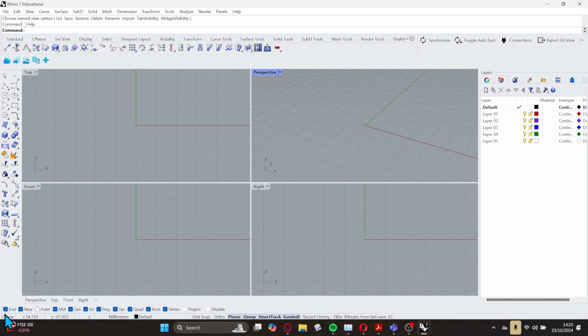Then as we start to come to the bottom of the screen here, we'll see that everything in Rhino exists within this workspace in the Euclidean mathematical calculations. So it uses X, Y, and Z coordinates to specify where you are. If I'm just hovering over here, can you see at the bottom of my screen it says I'm in the C plane, and then it tells me where I am in the X and where I am in the Y? Can you see that in the bottom left of the screen as you move your mouse?